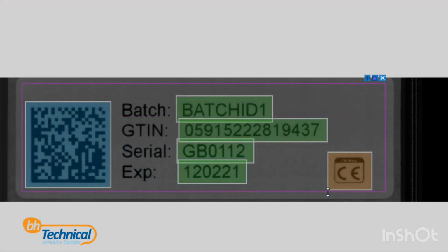If your area of blemish inspection has no printed information within this area, then there is no need for you to create an edit mask. Simply give the blemish inspection a name and continue on with the design of your template.